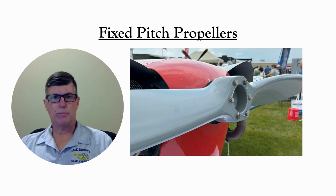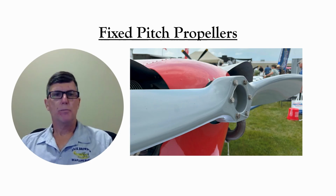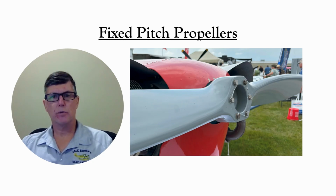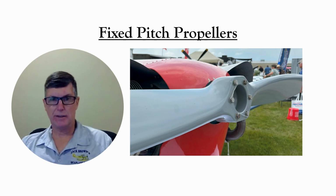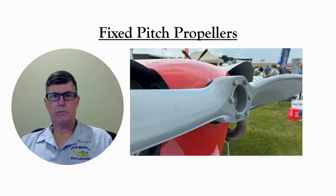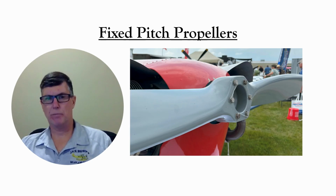A fixed pitch propeller is characterized by three numbers: the number of blades, the diameter, and the pitch. Pitch is how far forward the airplane would need to move per propeller revolution in order for the blades to have a zero angle of attack. For maximum takeoff and climb performance, a shallow pitch is better, which would mean a low number for the pitch.